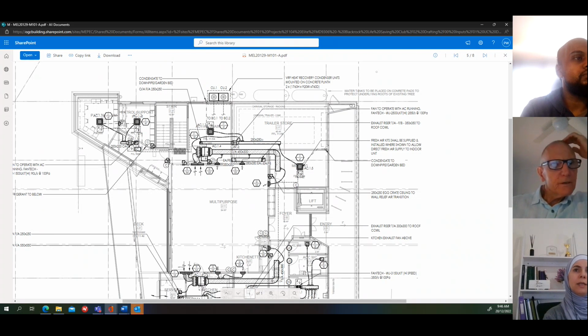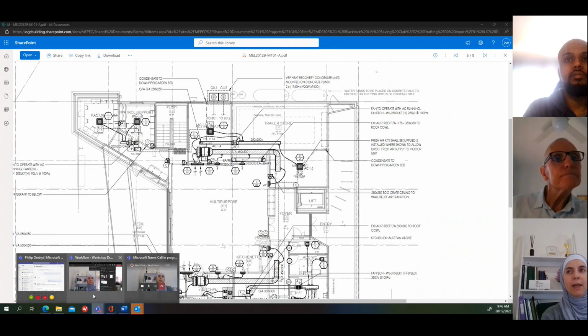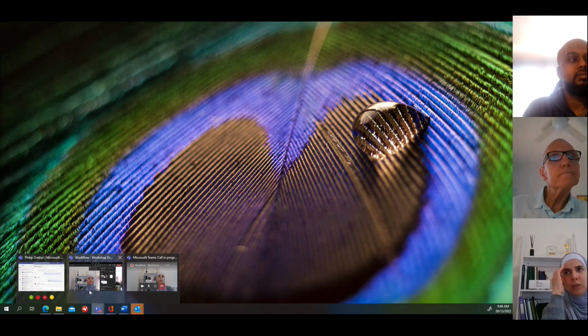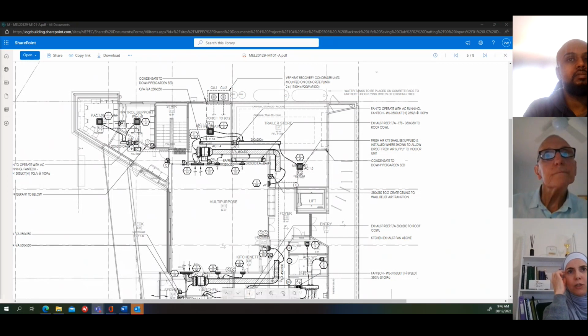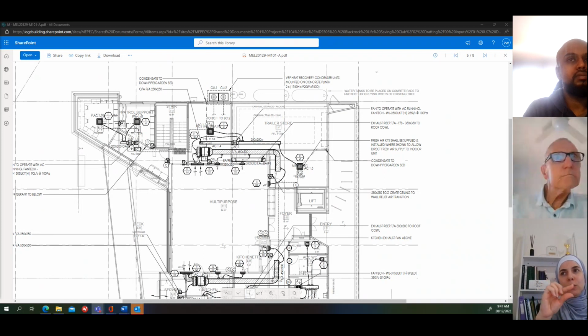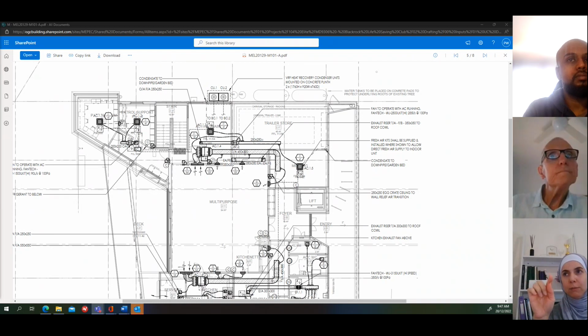Okay. So in this case, if we're studying something with the fan, for example, the fan static, or we're studying the duct size, if this is internally lined, we want to consider the actual path for the airflow, which is less than the written number, right? So to check if the velocity and pressure drop are as per standards.